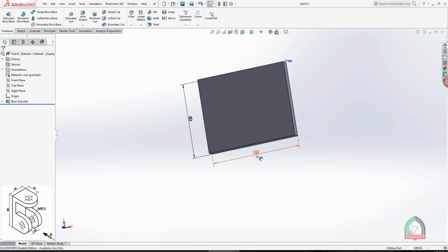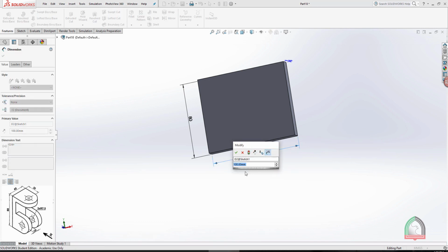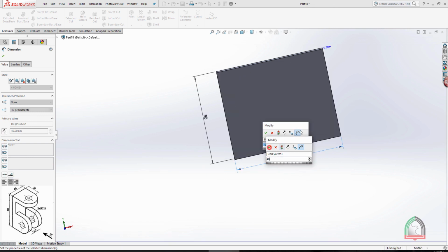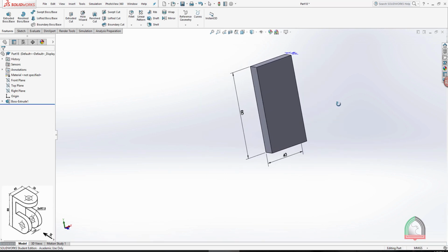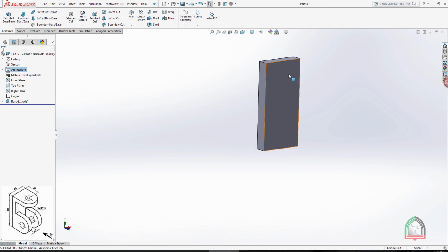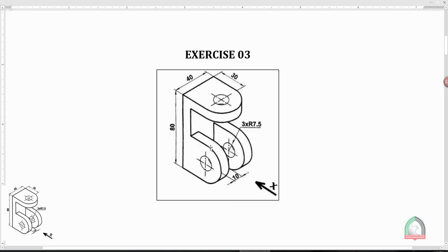So in order to enable this facility, you need to keep the dimension at the time of sketch. So I'm making it back to 40, changing to 40 here and regenerating it. So here is our old figure we have. I'm hiding this dimension for the time being. Now I need to draw this portion.